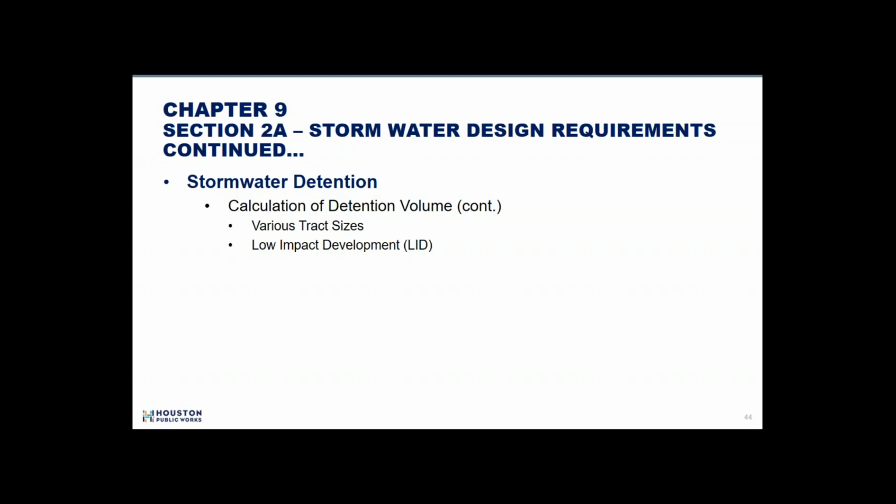The tract size will define the rate that you will use, whatever that is. Currently it's 0.2 and 0.5. In the future, it's probably going to be some other set of numbers. If you're working in a 5 acre tract, and you're developing 1 acre of it, only disturbing 1 acre, the tract size will define the rate, not the area you're working in.